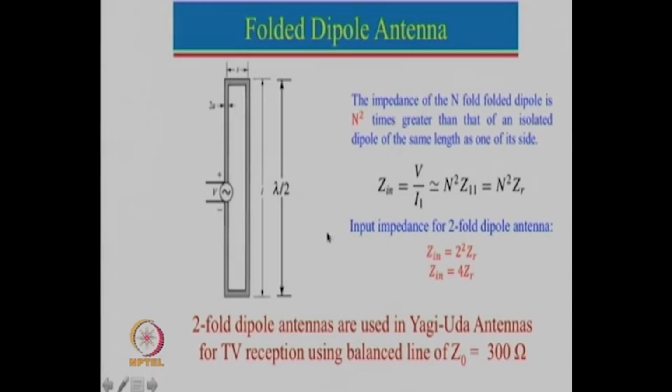In fact, it is kind of similar here. If this length is lambda by 2 and this is also lambda by 2, and if this is negligible, then the total loop length will be equal to lambda. But if this is increasing, then these dimensions have to be reduced so that the total loop length is approximately equal to lambda. So when we talk about loop antenna, we will bring this particular thing up one more time and show you what can be done with this.